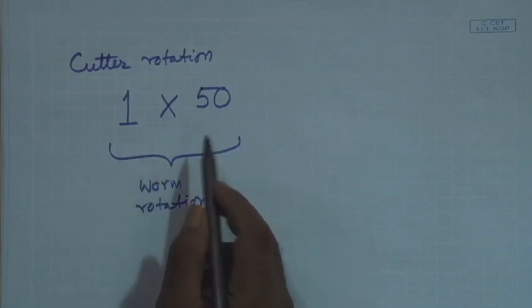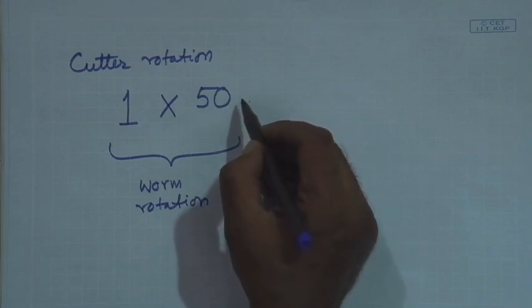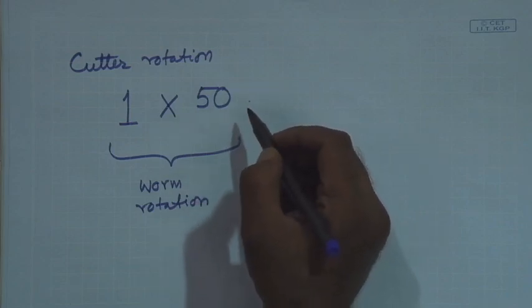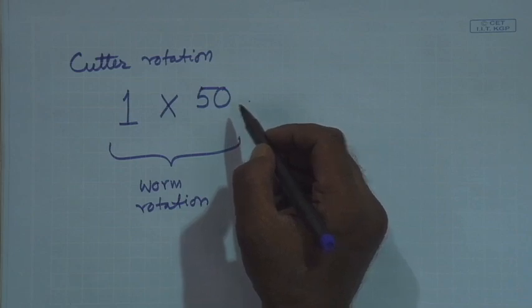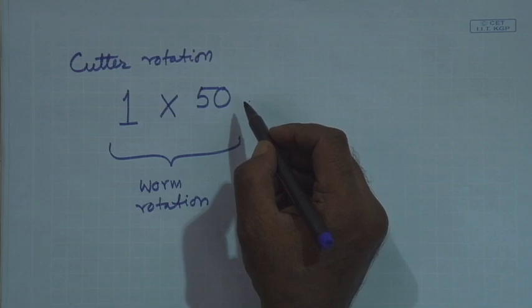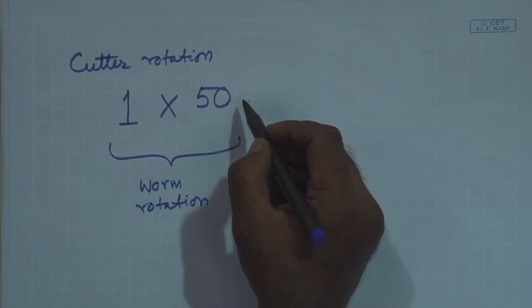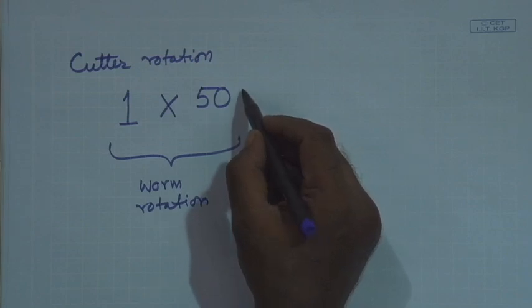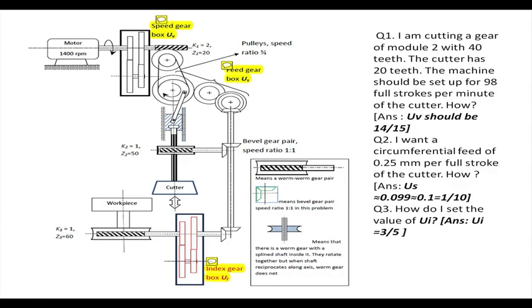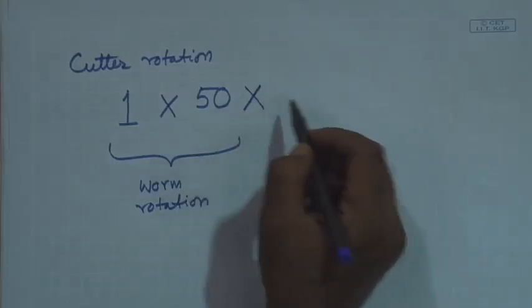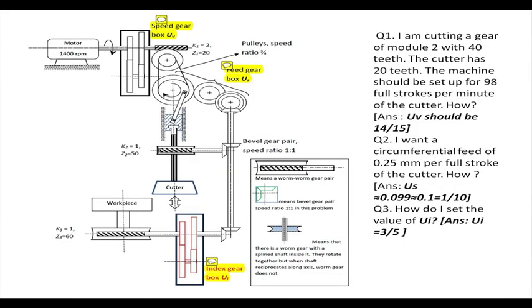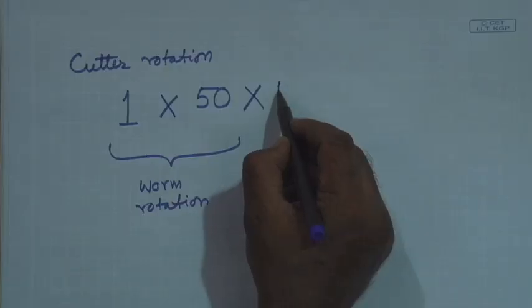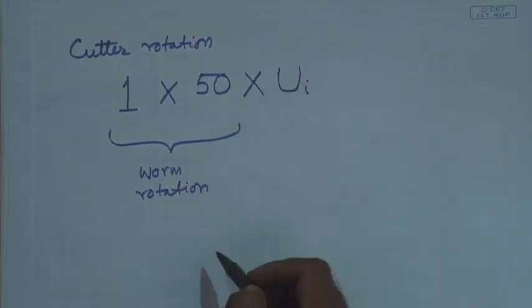Fine. After that, through the bevel gear pair, we come to the main line. It is just like a car backing off from a by-lane onto the main road. So, you are going in reverse, and after reversing you come to the main road, that means the national highway, and then you are moving forwards, and when we are moving forwards, all the ratios will again be taken as the straight ratios, not reverse. So, now we move through the two bevel gear pairs, come down and enter UI, so that at the output of UI this will be the rotation.